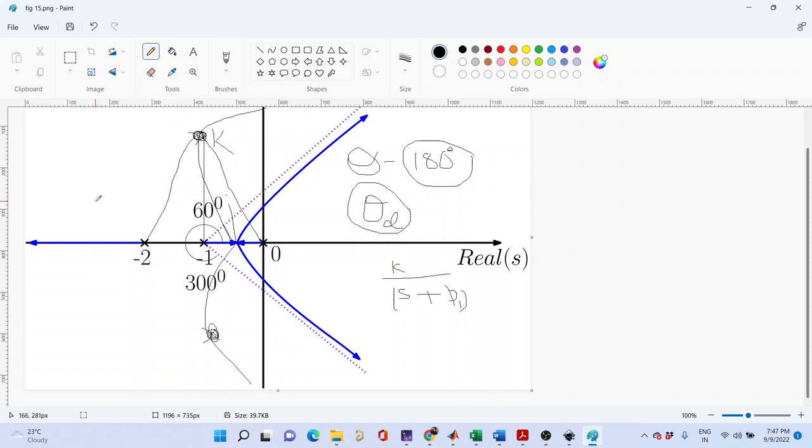It gives you information about the dominant pole dynamics. The Bode plot is not going to give you the dominant pole dynamics of the system. It will only help you in achieving performance criteria, such as the frequency range for which you need a high gain, or the frequency range for disturbance rejection. Those things will help you, but dominant pole dynamics is not represented, and there are several questions which cannot be answered through the Bode plot. So root locus gives you complete information about the closed loop dominant pole dynamics.